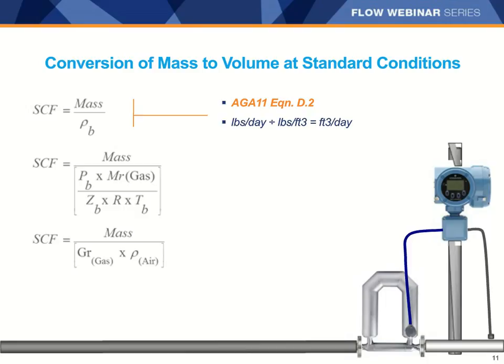On this slide are shown three different equations for the conversion from mass to standard volume, or SCF. All three are essentially the same relationship. However, they each show this relationship in different terms that can be found within the AGA standards. The American Gas Association publishes these standards, and they help us by providing equations such as these.